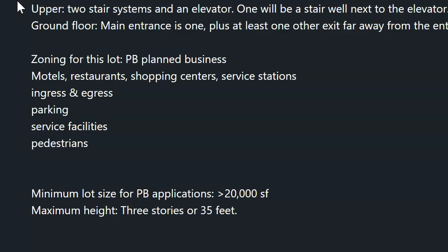So that's just a real quick rundown of some of the requirements for the Noblesville, Indiana, Lundberg Library project. You'll need to keep some of these in mind, mostly the ideas about how many staircases you're going to need and how many exits you're going to need. That is the main thing, and also what you're designing for. You're designing a structure for a maximum of 311 people, and it needs to be fire rated construction.